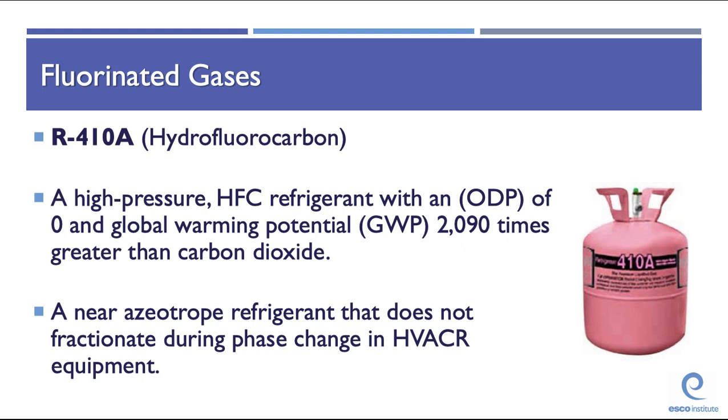One disadvantage of R410A is the operating pressures are approximately 50 percent higher than R22, and it cannot be considered a drop-in replacement for retrofitting existing equipment. Primarily, you will see this in comfort cooling: package units, residential split systems, and now some window units and dehumidifiers as well.